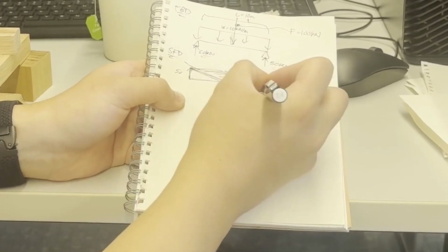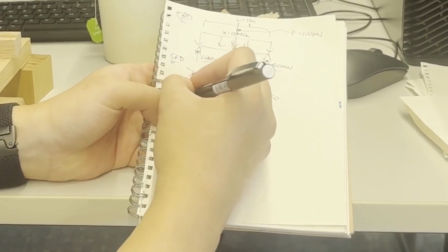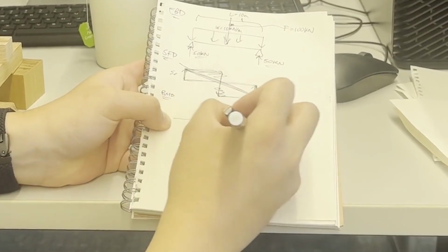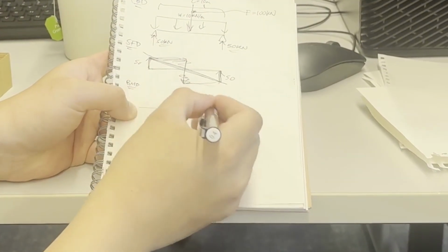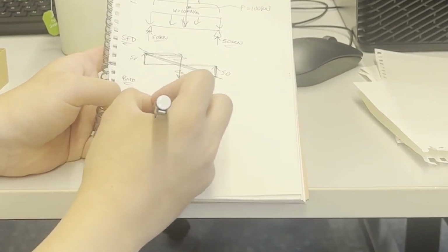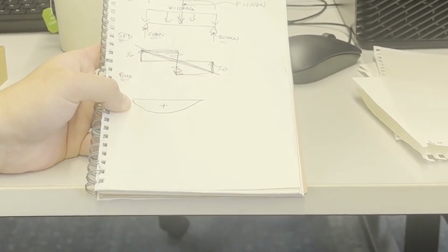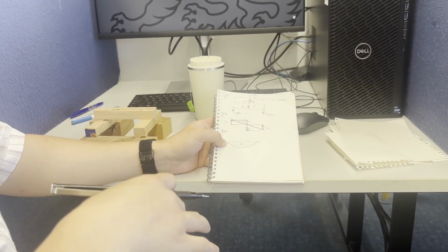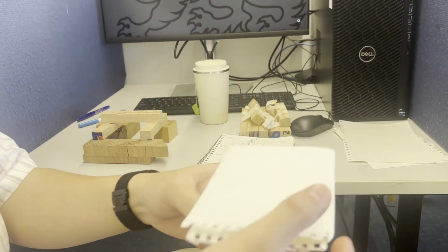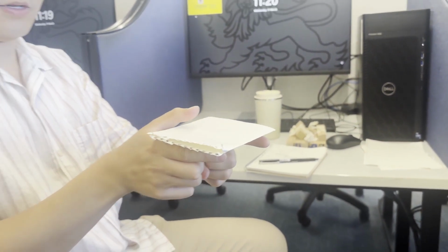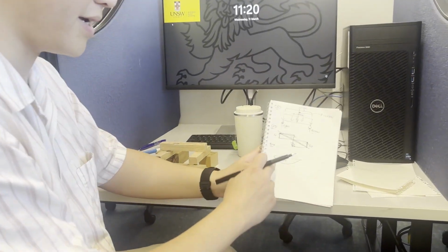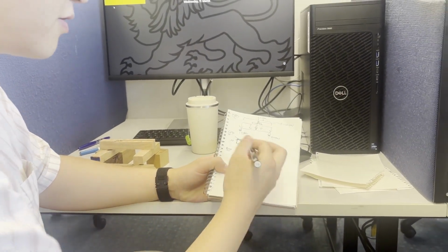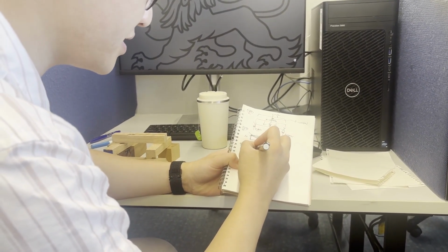The bending moment diagram: in previous classes, you might have seen it going positive as up, but here we flip it because it is a better indication of how the beam sags. Going back to the paper example, this is positive bending, and it's causing a positive deflection going downwards. So it makes more sense to flip the bending moment diagram to indicate the shape of the bending. It's also called the tension positive convention.